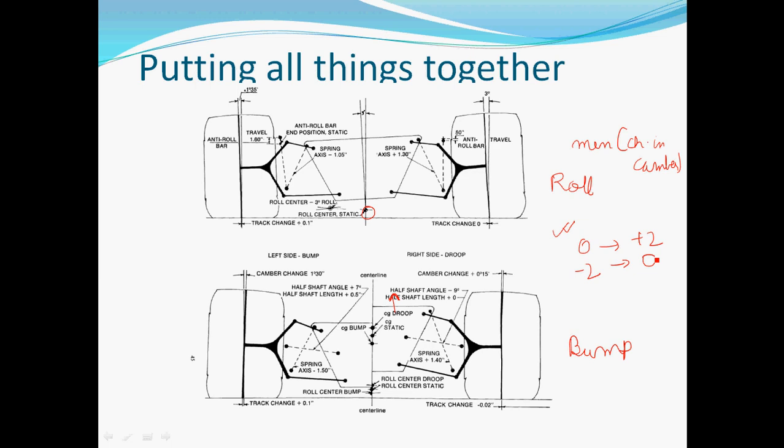So this is again very important. The choice of initial camber can give you an edge over your competitors. So I just summarize it. What is your evaluation criteria? You have to choose such dimensions which minimize your change in camber in the roll condition. Now, many ask me about the software to use, so I'll just give you one example.